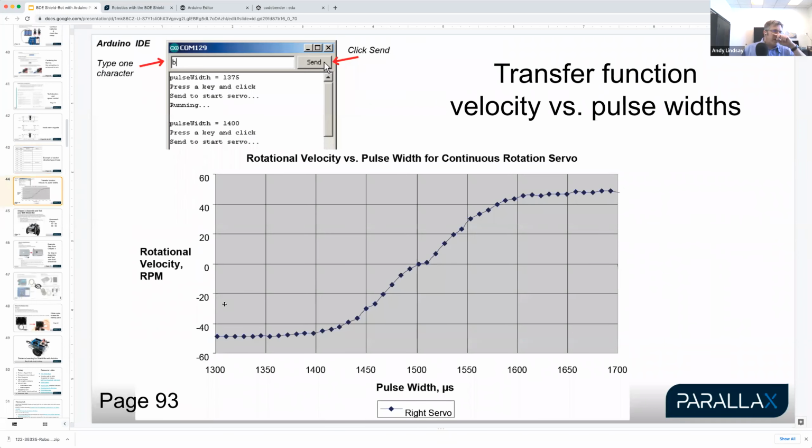And actually, there's also an activity in there where the students can measure how fast the wheel turns and graph it. And this is an example of the result of that activity where they're feeding different pulse widths, or what we call those brief high times, to the servo. And you can see that 0 RPM on the left here corresponds with 1500 microseconds. And when you're up to 50, you're kind of at half speed here. By 100 above, you're almost at full speed.